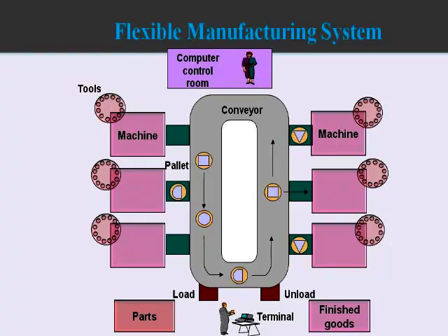Once the machine is processing the program, the tool selection and the tool life, how much is the remaining life of that particular tool, are all automatically recorded. In the automatic tool library maintained by the controller, all this data is appended. So we will come to know the remaining life of the tool on each machine.